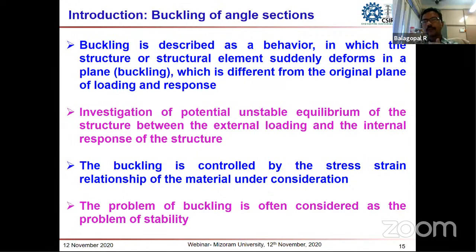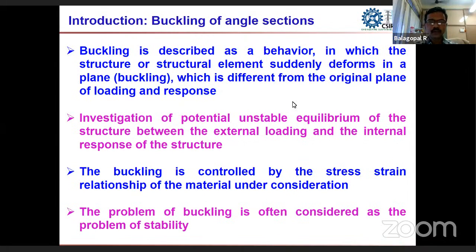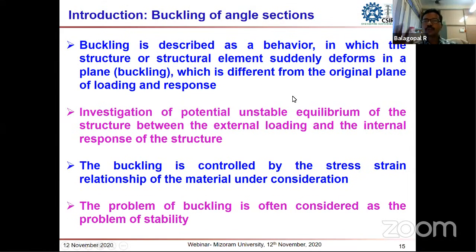Due to the unstable equilibrium existing between the external loading and the internal response of the structure, buckling happens. It is purely due to unstable equilibrium that buckling happens, and buckling is controlled by the stress-strain behavior of the material under consideration.